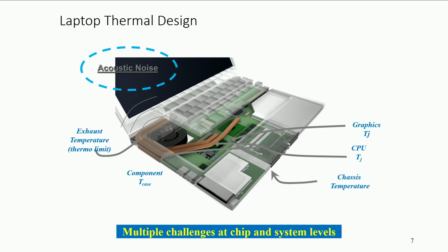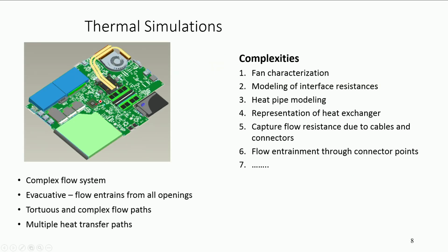So, what we typically do is, let us say this is a system, I will get this heat pipe and do some standalone testing, and I will measure the temperature here, here, here, here, and according to the temperature difference I will assign equivalent thermal conductivities.